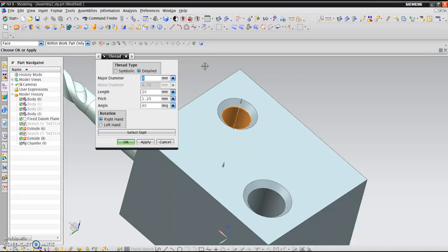Like I told you, whenever there's a failure in tapping, you need to analyze the risk and try to figure out the root cause, going one by one. Select the right cutting surface footage. It comes from the manufacturer's book. Again, each tap will be color coded based on the workpiece it will be used to cut.